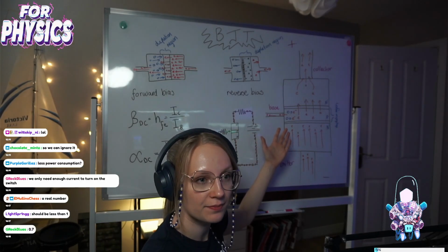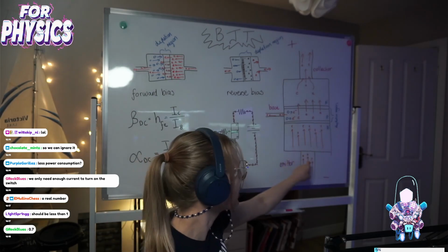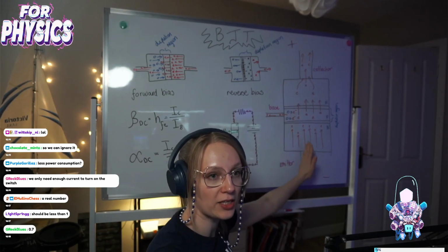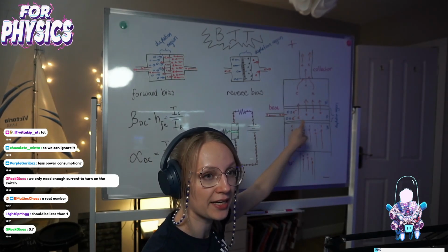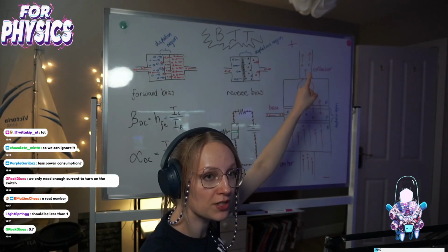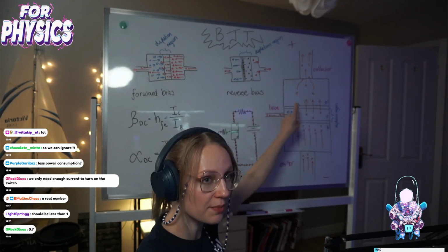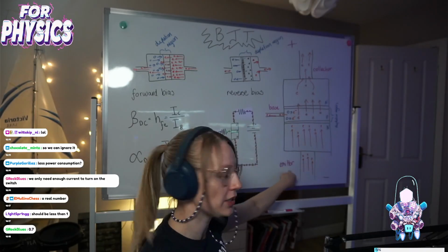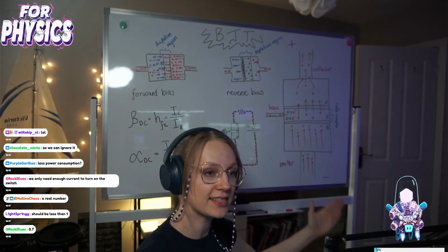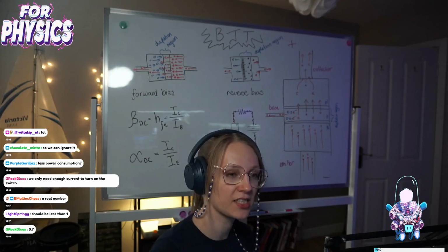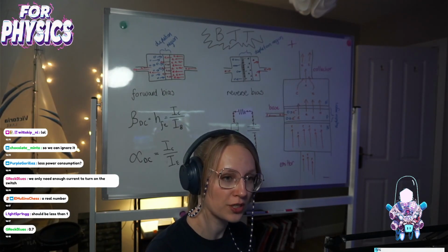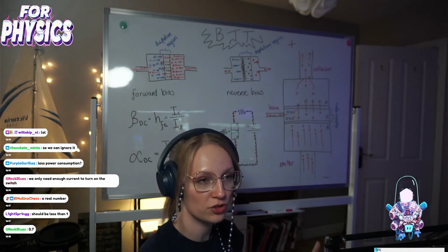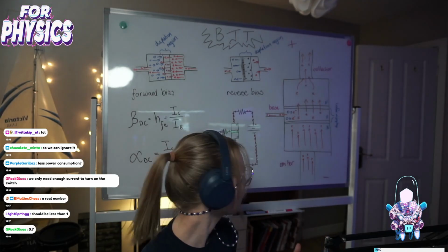Common sense, right? Okay, common sense is a bit rude of a statement. But can we agree on this? All the electrons coming up here have 2 paths to take, base and collector. So the sum of all the electrons in the collector and the sum of all the electrons in the base should equal the emitter. Classical thermodynamics, statistical physics. Energy cannot be created or destroyed. We cannot create matter out of nowhere. The electrons have to go somewhere. That's where they all are.